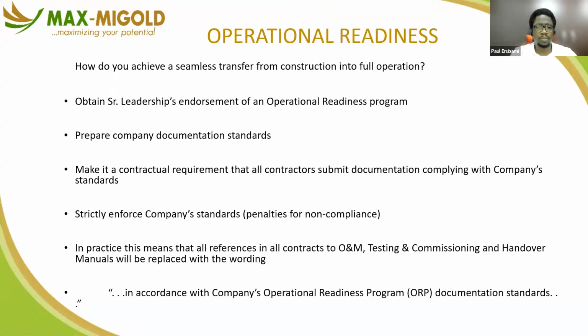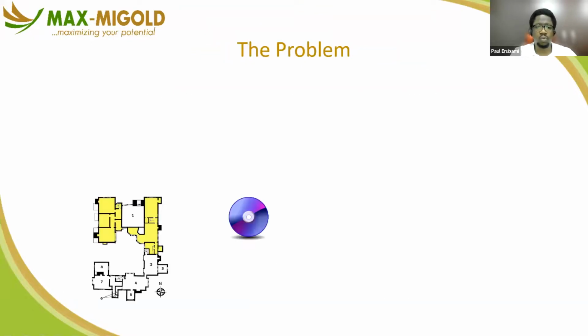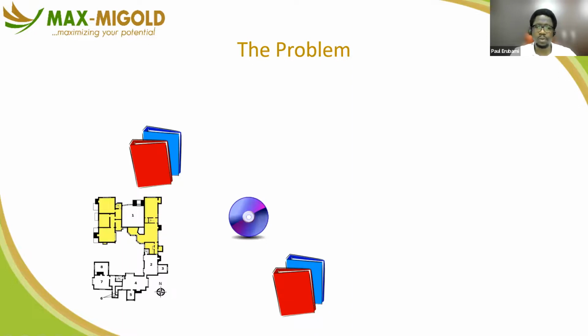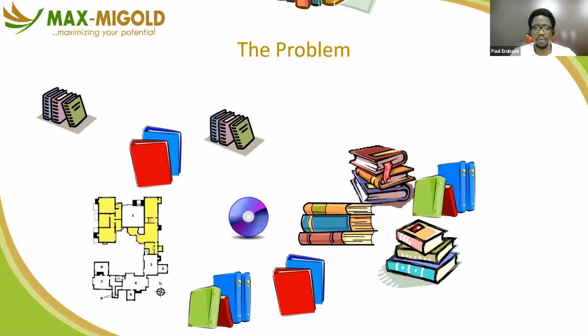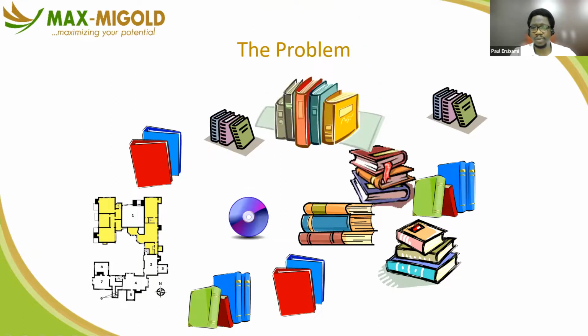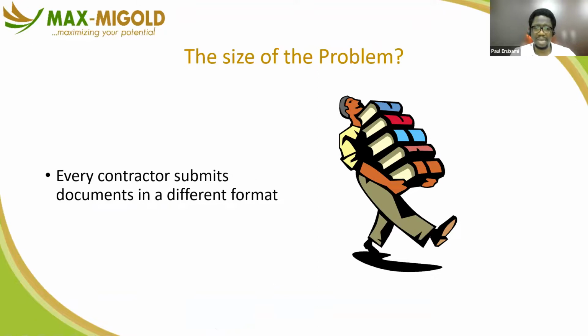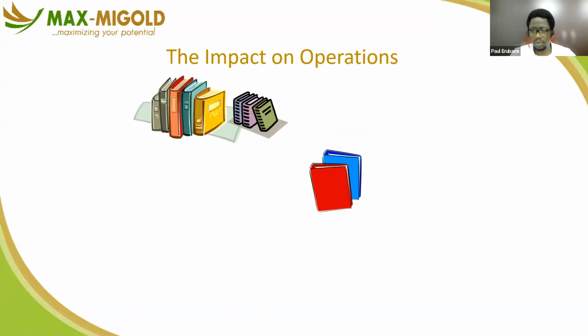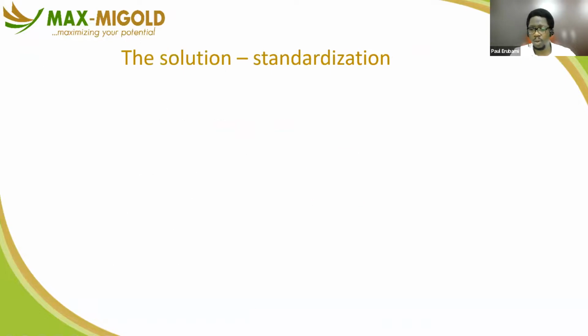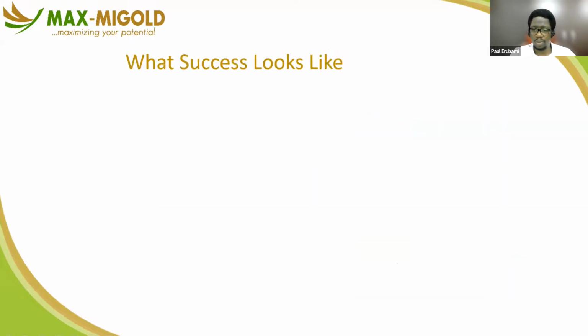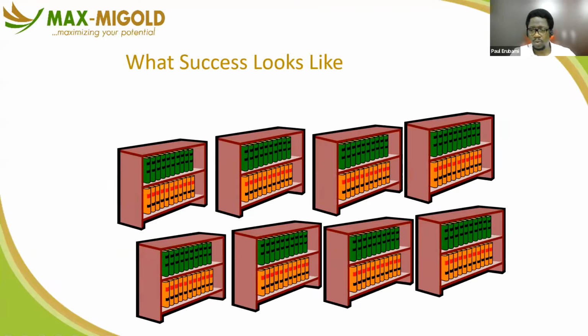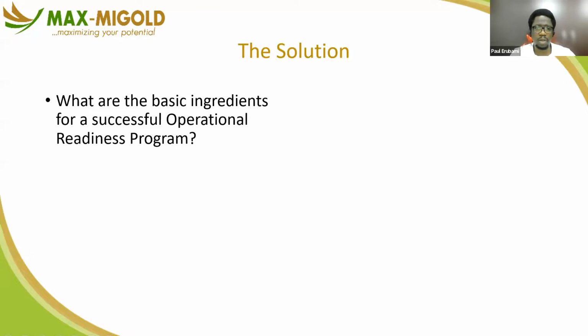So the process is something that you do to reduce challenges at handover. Consultants and contractors are happy to dump on you cartons of CDs, warehouses of paper documents in different disjointed formats, if you don't work with them from the beginning to say, this is the format we want things. We want these maintenance logs in spreadsheets. We want those in AutoCAD format drawings. I know you have your numbering structure or labeling structure. We just need to understand how the filing is going to be done so that we have all the information we need.